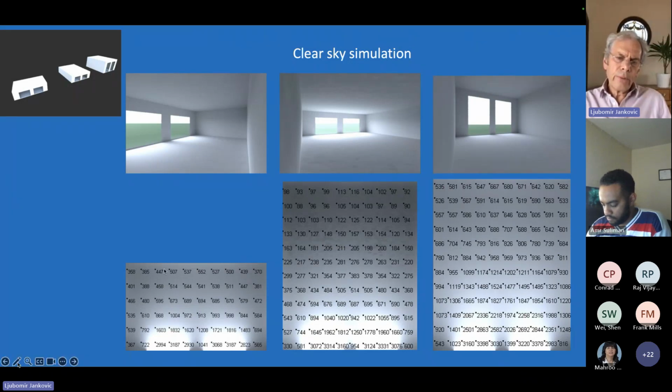And here there's more than that in the back of the shallow plan building, but in the back of the deep plan building, there's far less than 300 lux. If we double the height of the deep plan building from 3 meters to 6 meters, then we've converted a deep plan into shallow plan effectively, and we have a decent amount of daylight in the back.